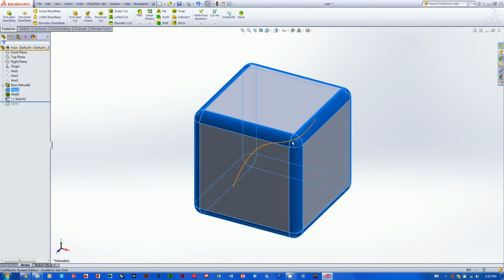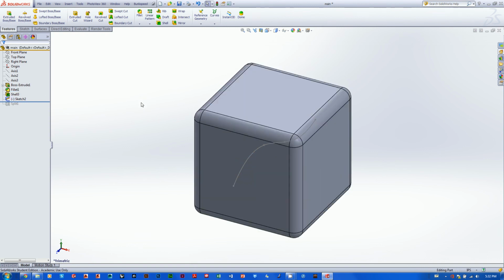We want to keep the fillet we added. We took a long time to decide this fillet. We just want to make sure that it fits into the design tree before the shell. So we just drag it up to the position we want. Now that it's landed before the shell, our whole shell is going to have this fillet included in it. And if we go over the shell, we see there's our preview, and you can see that the fillet continues on the shell as well.